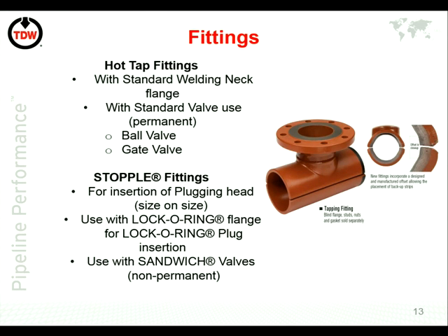So the fittings that you've got, these are just typical fittings. You'd have a standard fitting, or you can have a valve use, so that's when it becomes more permanent, and that can be either a ball valve or a gate valve. And the stopple fittings, obviously for the insertion of the pig plugging head, that has to be size on size.